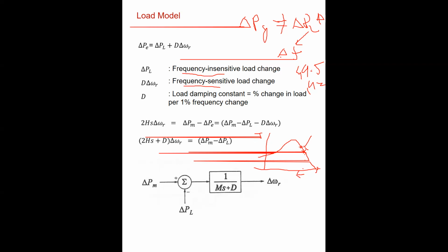Positive effect means, because you see, if the load has increased, then the entire power has to be made from the source, from a generator, right? Am I right? But from the motor side, what happened? If the frequency has reduced, the electromagnetic torque has changed. And thus this change in the torque is having a positive change in the power output in the system. That is from the motor behavior basically. So this is having a positive effect.